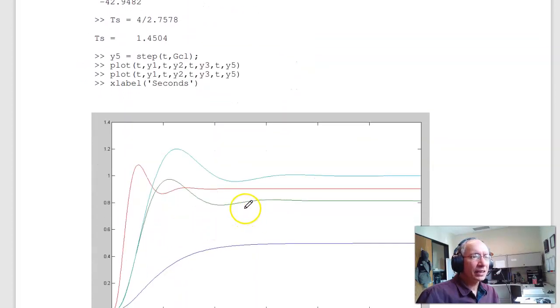Plot, and here is your gain compensator. It's problem 1. Problem 2, gain compensator. This is your PI. And here's your lead. So the PI compensator is a little bit slower than the original system, but there's no error for step input. There's nothing stopping me from adding a second lead compensator and speeding it up some more, but for this homework set, that was good enough.